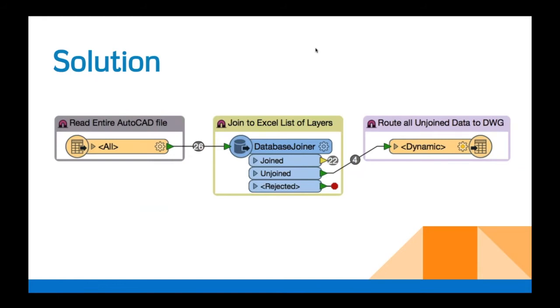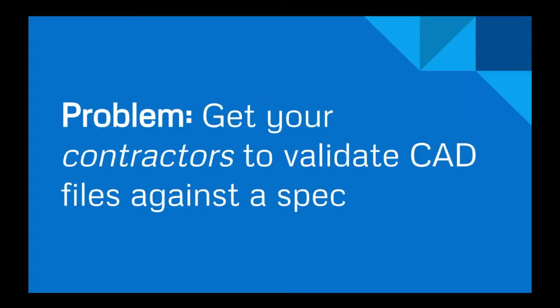Now you can do far more sophisticated QA looking at geometry. There's a geometry validator. There's attribute validators where we could say we need specific things there or not, but I just wanted to give a sense of that. Now that's all fine and good, but how do I leverage that? If I make that setup, how do I let others use that without necessarily knowing how to use the Workbench tool I was showing or all of FME?